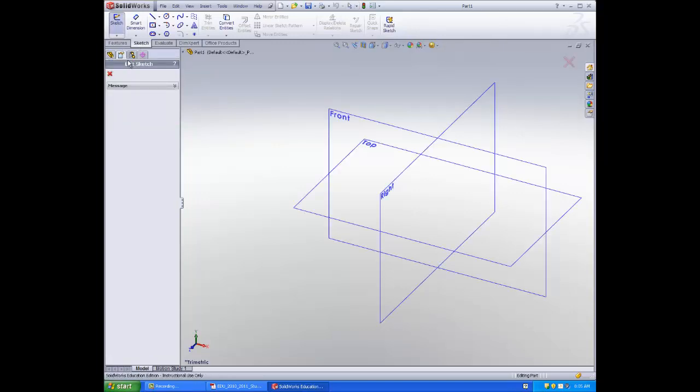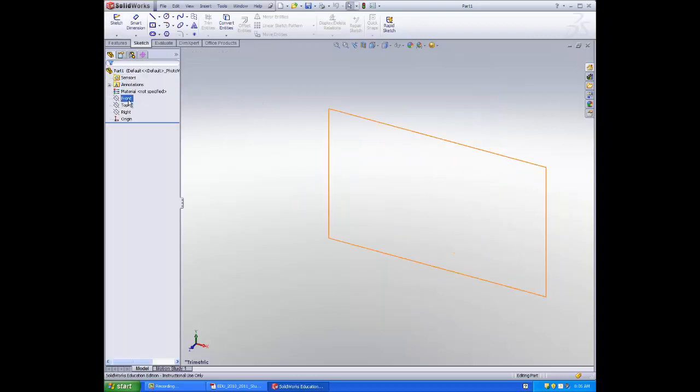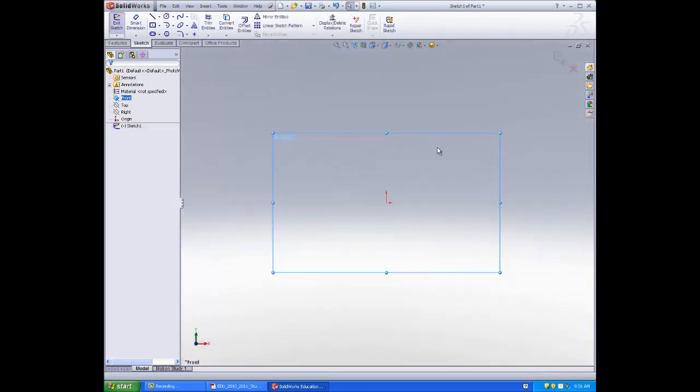So we have it open in Sketch, and we go back and select our front plane. We have our front plane, with top and right also available. And we see over here our confirmation corner showing that we're using our sketch tool, and we can exit out of it if we don't want to use this, but this is our confirmation of where we're at in our design process.